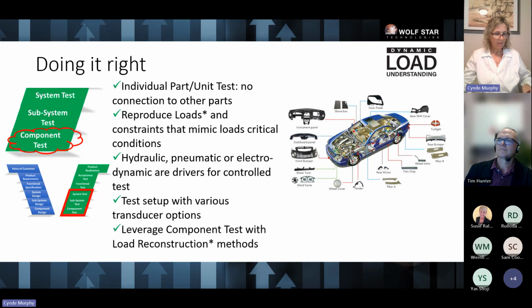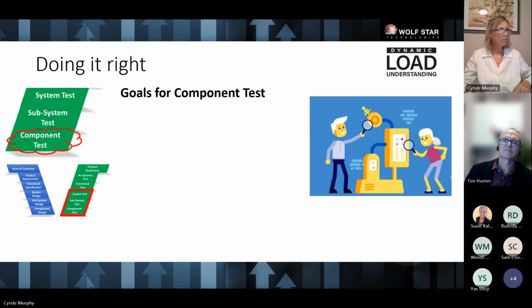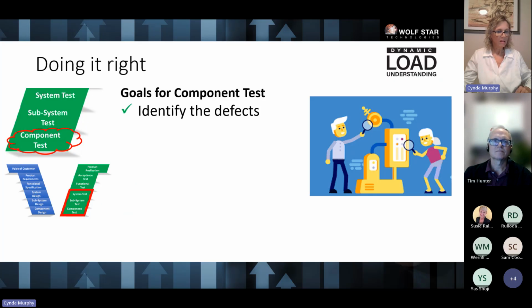And again, loads come from vehicle measurements or from load reconstruction methods. With load reconstruction, both magnitude and direction are calculated. The main goal of the component test is to determine the defects. You would run the test long enough or load it enough to induce part failures.